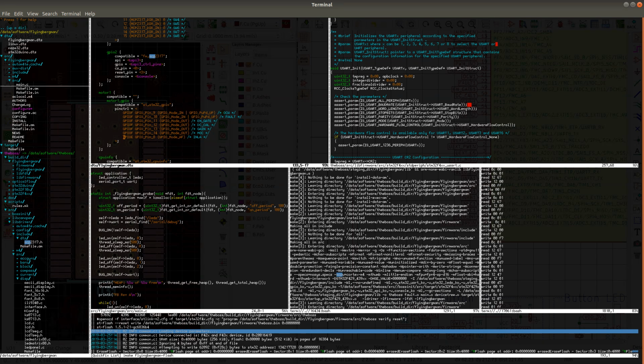So if you set the speed higher than you need, then you're going to have unnecessary EMI on the PCB traces that carry that signal, because you're going to have much faster slope. So a general recommendation is to use the value that's as slow as possible. And in this case, we're going to be running at 30 kilohertz, so we don't need anything above 2 megahertz. So we can set the I/O speed to 2 megahertz.